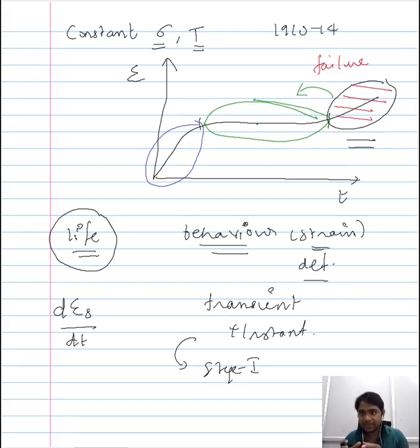Once the material begins to deform excessively, and the rate of its deformation increases, it means that the material has now moved into the tertiary stage from the steady state stage. And once you realize that, instead of allowing the material to fail, you stop the application and then you replace the high temperature material. And for this reason, the creep test generally will not continue till the material fails.